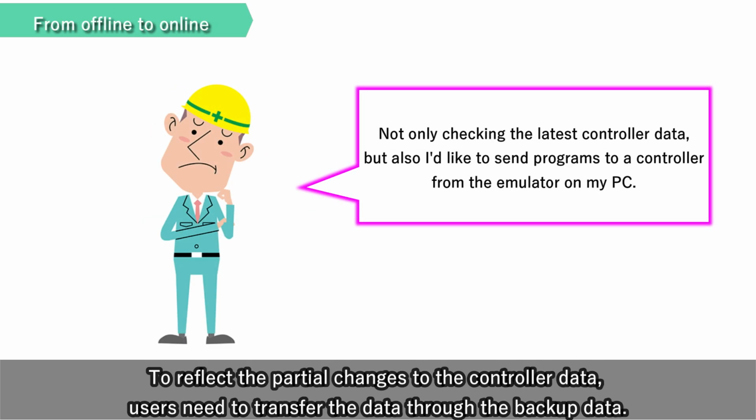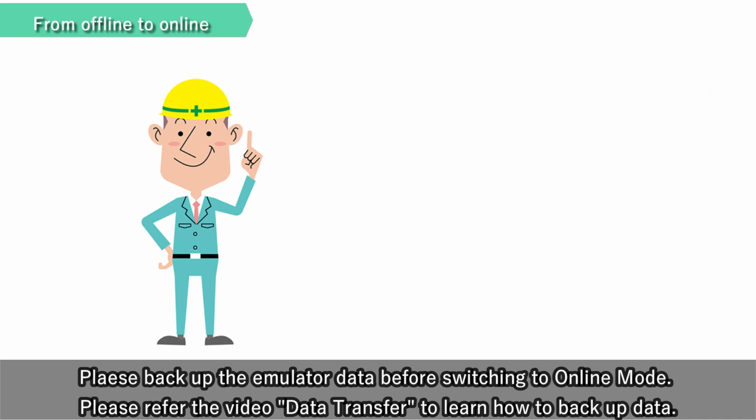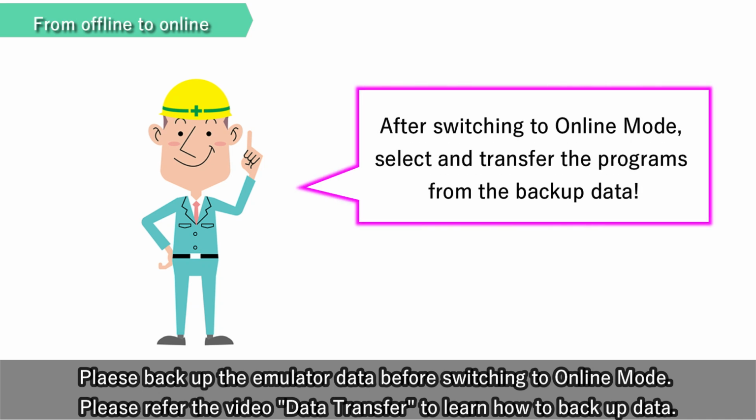To reflect partial changes to the controller data, users need to transfer the data through the backup data. Please back up the emulator data before switching to online mode. Please refer to the video Data Transfer to learn how to back up data.